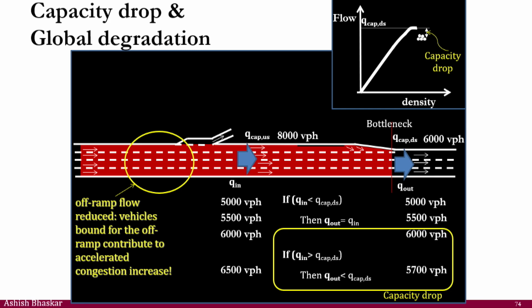When you are doing mesoscopic modeling, which normally we should be doing for Indian conditions, you should start with mesoscopic first before going to micro, because micro has far more parameters to calibrate, since you are trying to capture individual driver behavior. Whereas in mesoscopic, you are capturing how traffic flows from one section to another. So in that case, yes, a side friction will create a bottleneck.